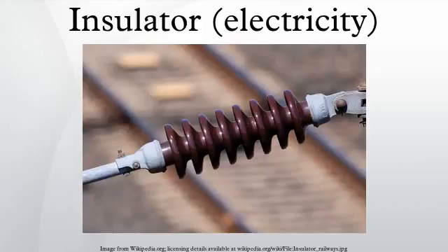Some insulator manufacturers stopped making glass insulators in the late 1960s, switching to ceramic materials. Recently, some electric utilities have begun converting to polymer composite materials for some types of insulators. These are typically composed of a central rod made of fiber-reinforced plastic and an outer weathershed made of silicone rubber or ethylene propylene diene monomer rubber. Composite insulators are less costly, lighter in weight, and have excellent hydrophobic capability. This combination makes them ideal for service in polluted areas. However, these materials do not yet have the long-term proven service life of glass and porcelain.